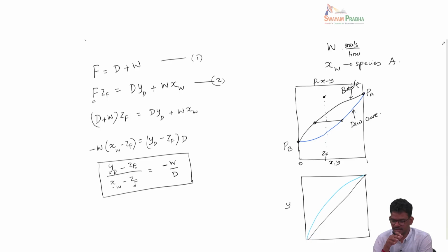When I reduce the pressure, I come along this line and touch this bubble point. Okay, so bubble point is where the liquid will first form its first bubble, and the first bubble will have a composition corresponding to this point. But that is making only one bubble, and you want to have a sufficient amount of vapor. So you have to go further down. Let's say you come somewhere here. This is a two-phase mixture, and these would be the corresponding equilibrium vapor and liquid compositions.